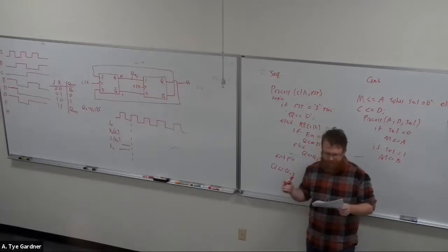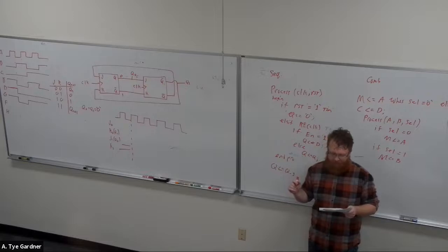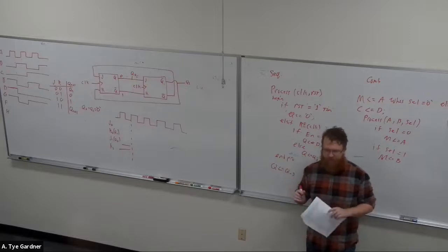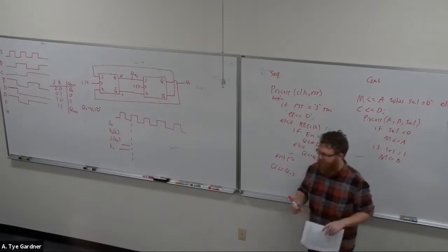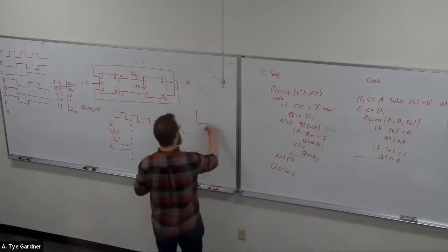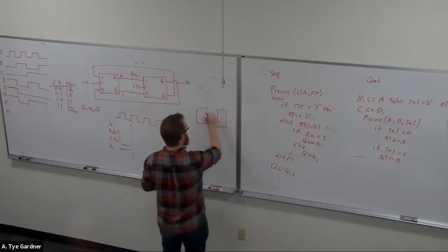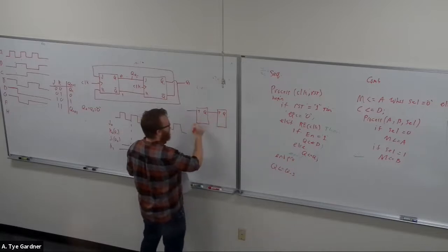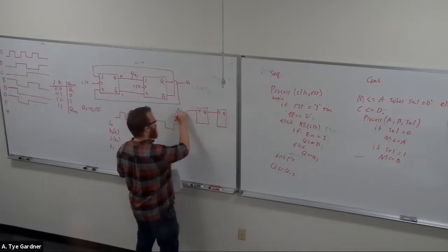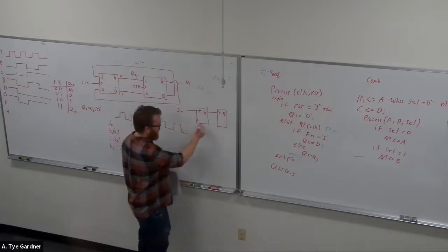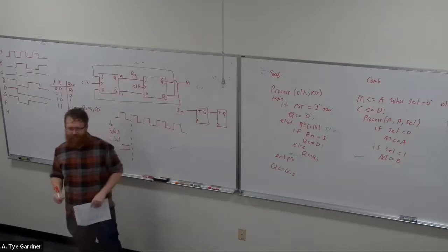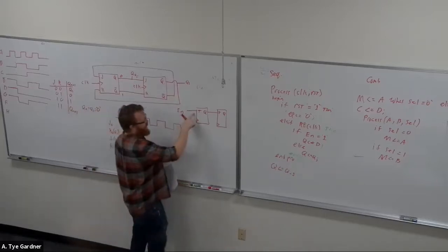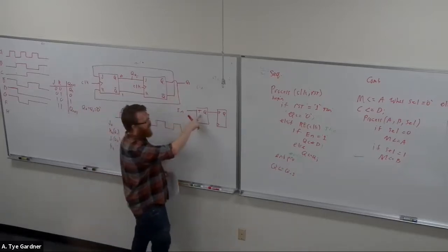This question is right out of the notes. The next one is: draw me a 3-bit synchronous counter using T flip-flops. We talked about it in the notes. T flip-flops just toggle. That might work, I don't remember. We just have to figure it out, because if enable is true, then the output is going to toggle.